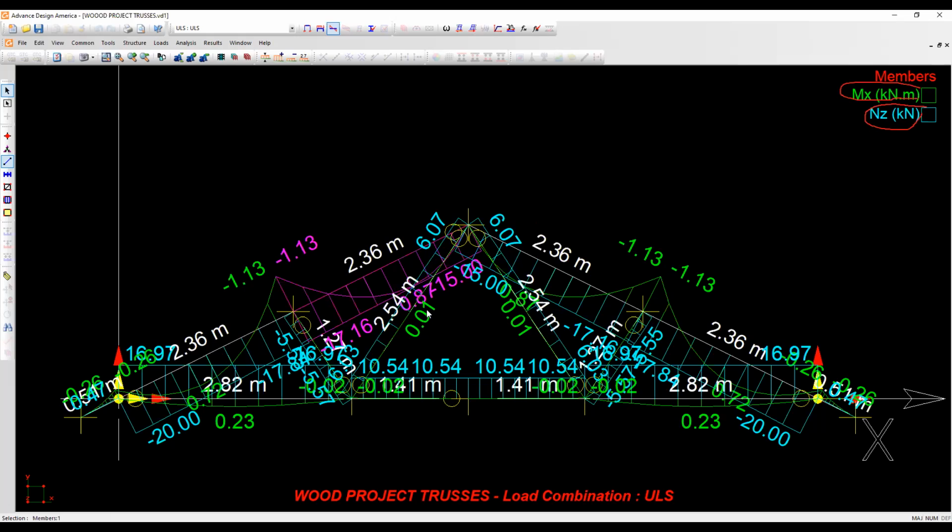Okay. Here you see that it's drawn like this. The reason why it's drawn like this is because it's positive, and this program says that when you have a positive axial force, you have tension. That's what the program is telling you. That's what the graphic is doing. So they decided that positive was tension, and therefore, if this member ended up having an axial tensile force, they would show it above the member. That's how they're drawing it. Now, what's important for you is that here you see a positive value, so that's where they draw it above the member.